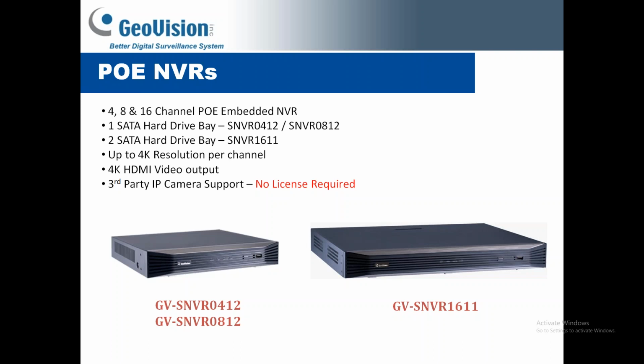We do have some Linux-based NVRs as well. These have a built-in POE switch. They currently are offered in 4, 8, and 16 channel. Some unique things about GeoVision's Linux-based POE NVRs is each channel can support up to 4K resolution, and you can put any camera on these units on VIF, whether it's GeoVision or third-party, with no license required. So the VMS software, you know, that you do have to have a license for, but these units don't run the VMS. They run a more basic view and record software, and no license is required for these units.